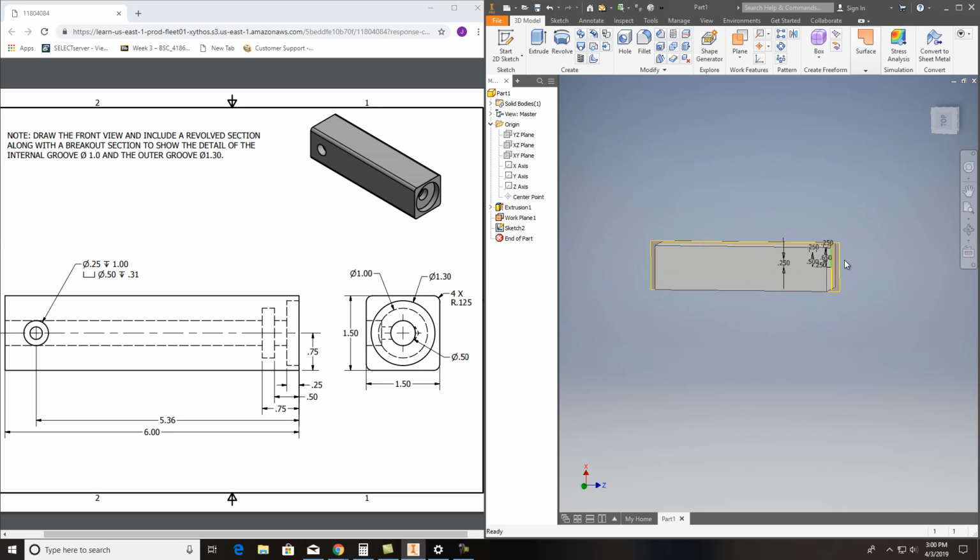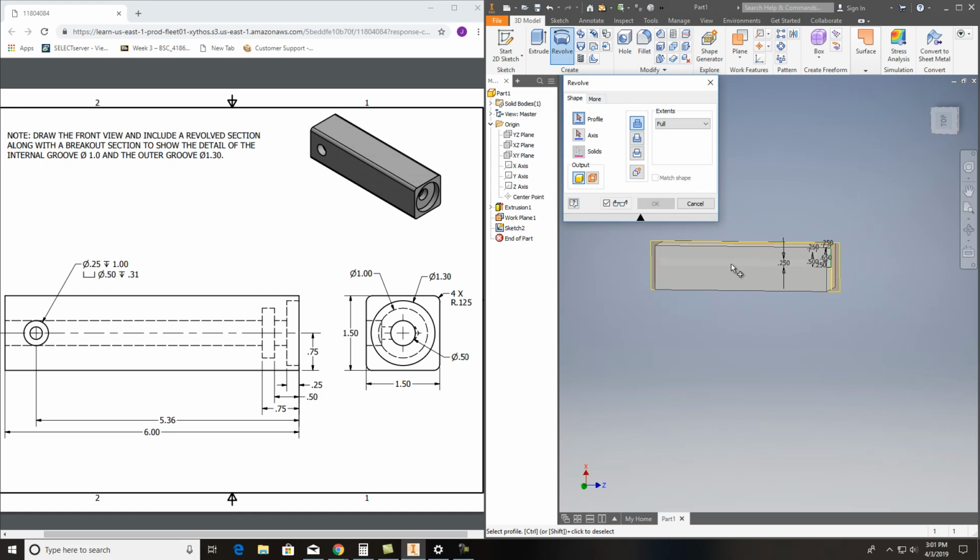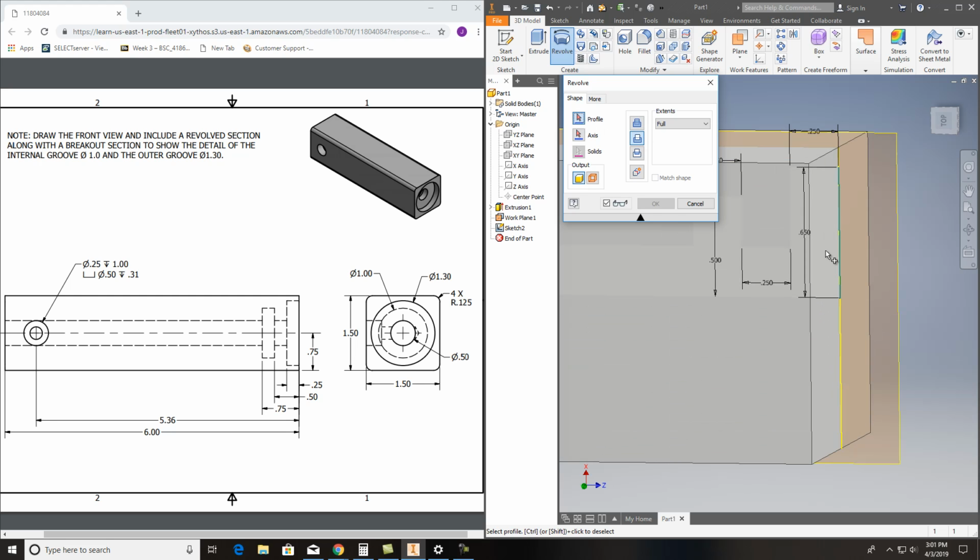You can't see it. It acts like it went away. I'm going to hit revolve up here. It's just where we slice that. I hit revolve, and I'm going to hit cut in my profile. I'll come in here, and you can see how it kind of highlights. But you can hit F7 again.